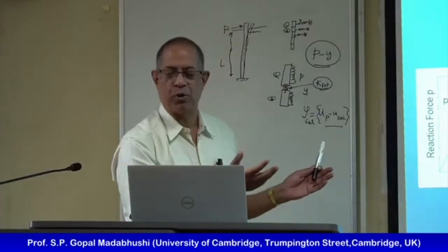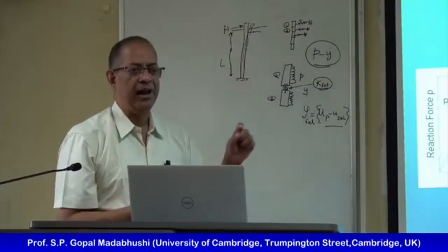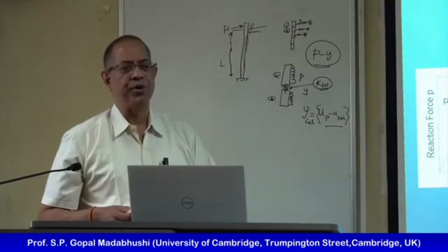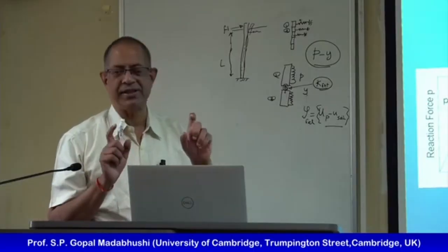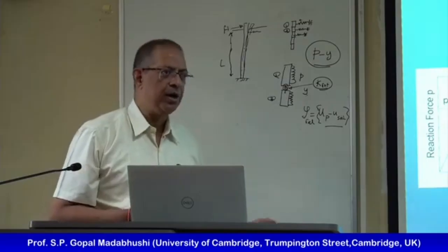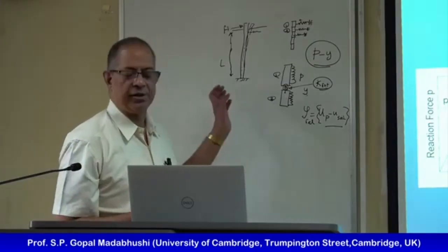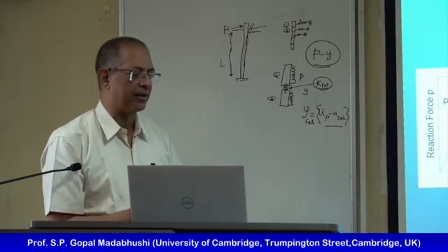But it's exactly the same concept as this. This was originally developed for lateral load on piles, but what we are now saying is our load action is not coming because of some external load, but it's coming because of the soil trying to move downslope. Okay, in the context of lateral spreading.